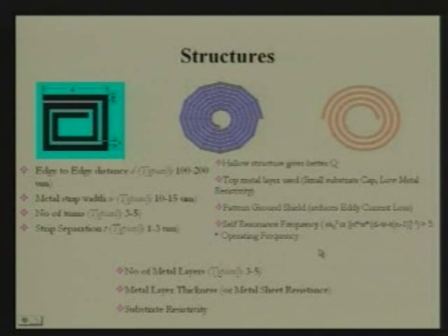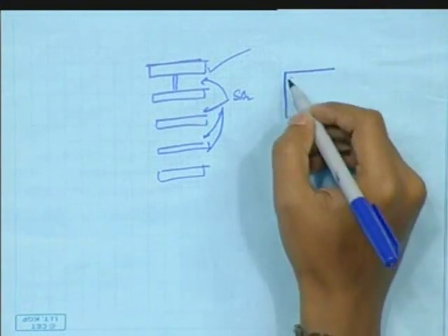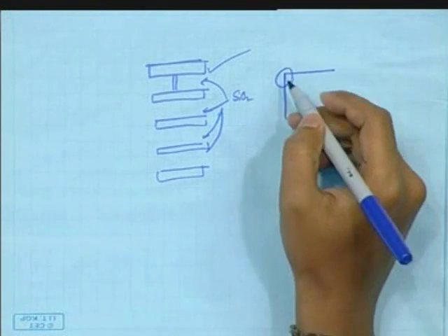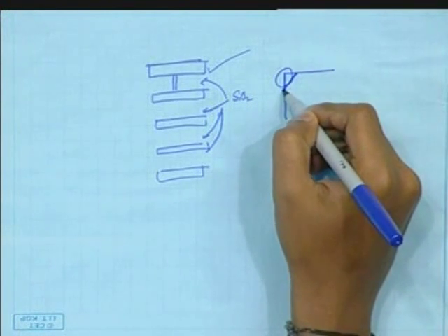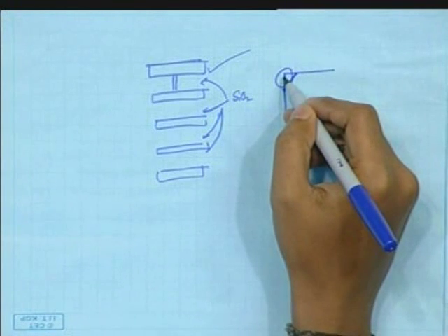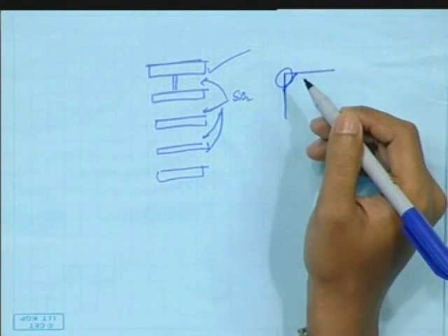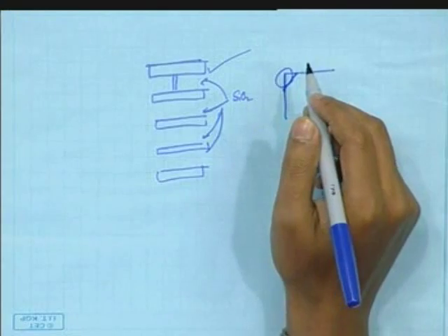Okay. Now the problem with fabricating such a square inductor comes from the technology point of view, because we use photolithography to etch out parts of the oxide, or to get the masks where to do the metallization. It's very difficult to get exactly a square portion. This edge matters, as Ashu has already told, that we often cut the line so that we don't get an edge. So there are various structures of the inductor depending on that.